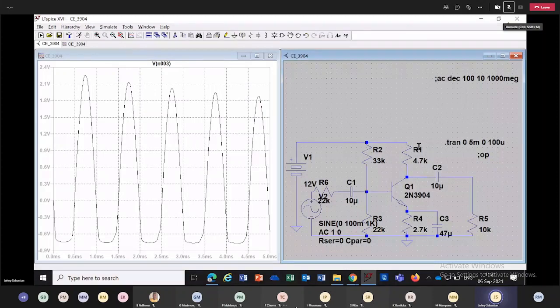Voltage across RC is 7 and voltage at the collector is 4.9. Voltage at the emitter is 4.06. So the negative signal swing is from 4.9 to 4.0. Negative signal swing allowed currently is around 0.9 volt.